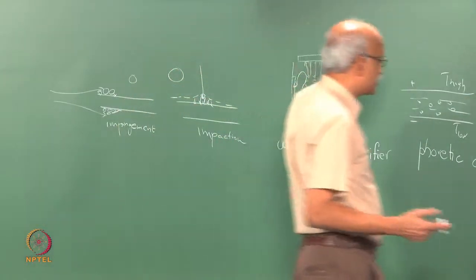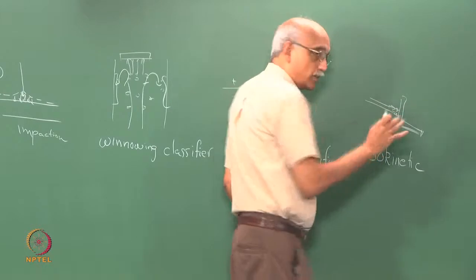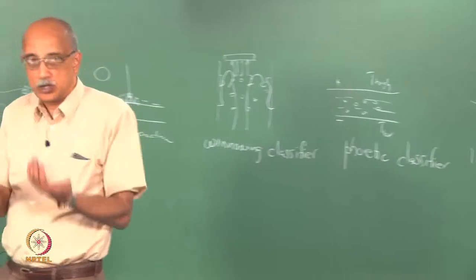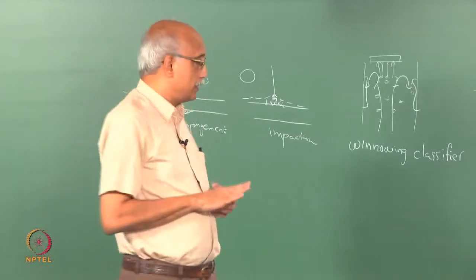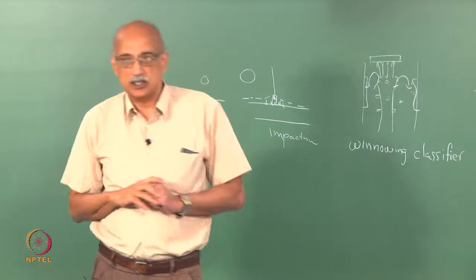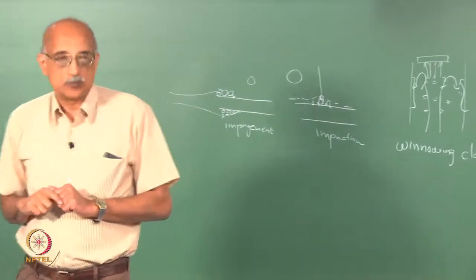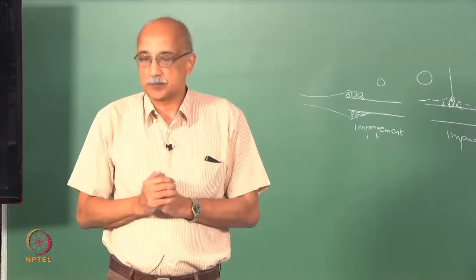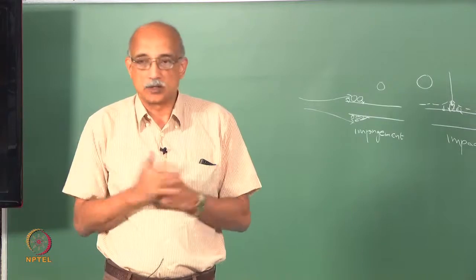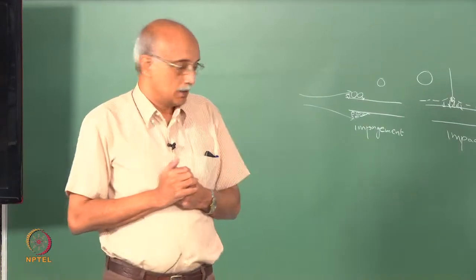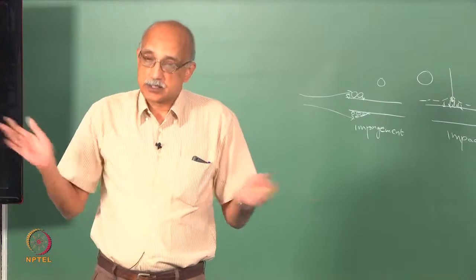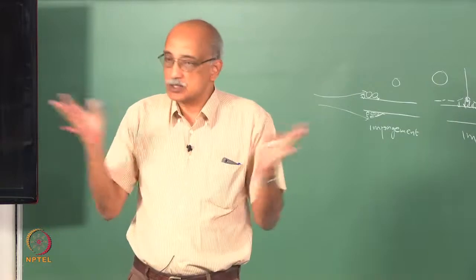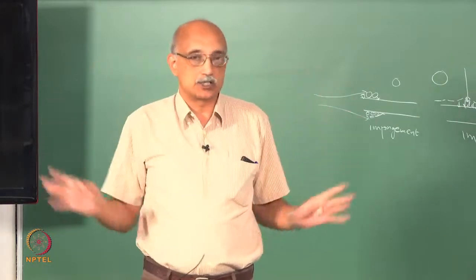Again, filtration pretty much depends on a normal entry, perpendicular entry of the airflow onto the filter surface. So, isokinetic sampling simply refers to really understanding the airflow configuration at a particular location and making sure that your setup is optimized for collecting particles at that location. So, in a room like this, you may need to set up multiple samplers and all at different orientations, configurations and so on to get a really good description of what is happening.